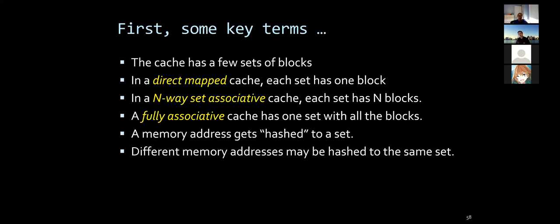So there are different ways you can store that meta information. And that's why the different types of caches exist. One is a direct map cache. Essentially, a direct map cache is very simple. You look at the address of the memory, and then each memory address has a one-to-one mapping. It means that for each address, it can only be in one block of the cache and nowhere else, right? It's a very easy mapping scheme.